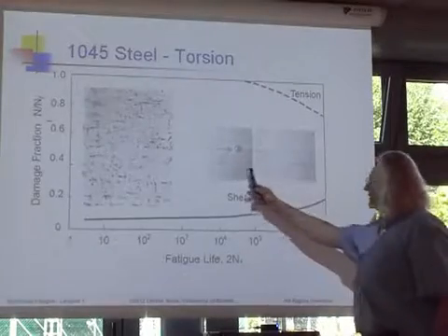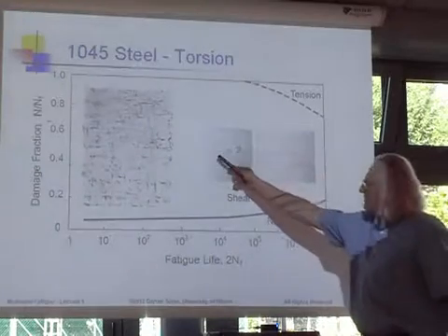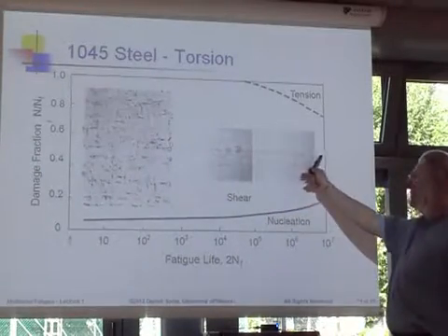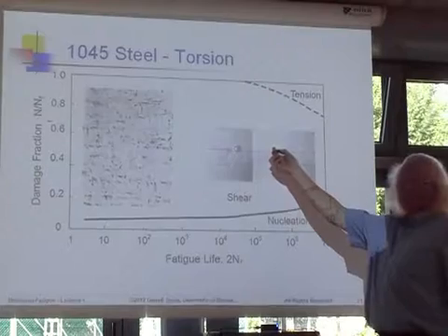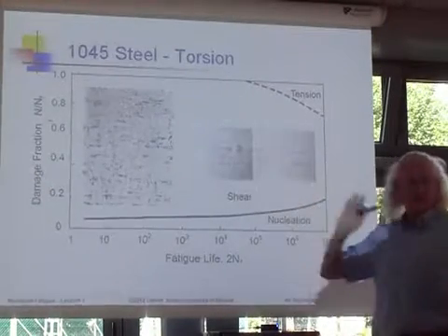And out here at long lives, you get these very long cracks which appear very long on the surface, but of course that's not the crack length we are interested in. We are interested in the crack that goes this way into the depth, and that's not a very big crack. You see something that's very, very different.